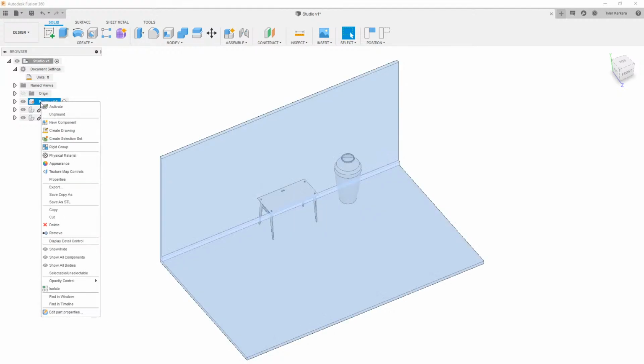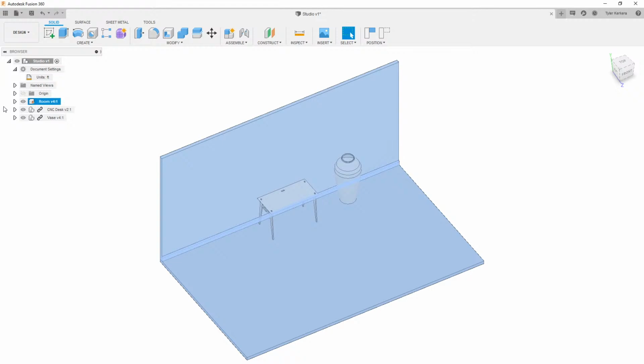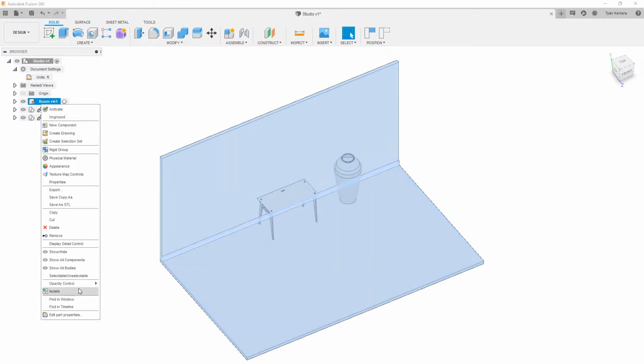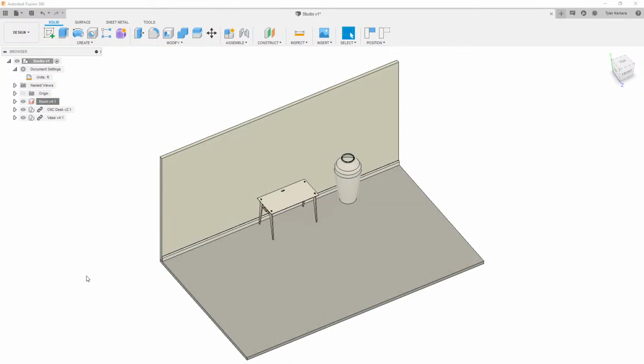What you can do is right-click on that component, and let me make sure I'm in the right place. I am. There's an option for selectable, unselectable. So you'll see when I do that, it now has this little circle with a cross through it on the actual component, indicating that now it's not selectable. So as I hover my mouse over that background now, it doesn't flash at me. I thought that was the smartest thing.